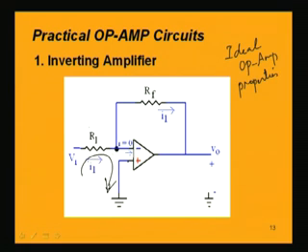Kirchhoff's voltage law we can apply in this loop also. This is a closed loop. It is coming from the plus terminal of V1 to ground and the minus of V1 is also grounded. So, this is a closed loop. If we apply Kirchhoff's voltage law to this loop, it will become V1 minus I1 into R1, and there is no other drop, that is equal to 0, because this voltage is grounded, they are the same voltage.